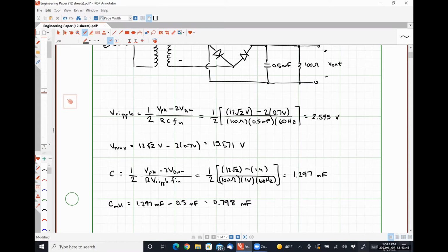And if you never allow your capacitor to discharge, which literally cannot physically happen, that's the only way you're going to get a pure DC signal out. So the larger your capacitor, the smaller and smaller your ripple will be. Yes. And so you'll get essentially close to a pure DC out. But with a voltage regulator as the next stage, it's really not important. As long as your ripple is below 10% of your peak, that's usually good enough to throw it into a voltage regulator. And then you would see only a couple of millivolts of variation at the output.